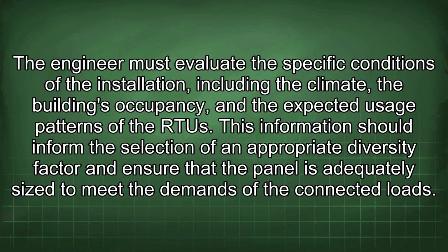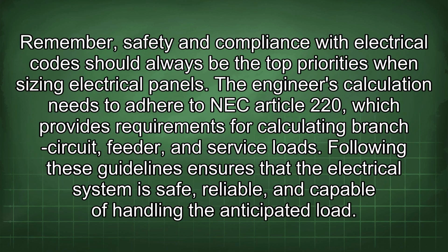The engineer must evaluate the specific conditions of the installation, including the climate, the building's occupancy, and the expected usage patterns of the RTU. This information should inform the selection of an appropriate diversity factor and ensure that the panel is adequately sized to meet the demands of the connected loads. Remember, safety and compliance with electrical code should always be the top priorities when sizing electrical panels.